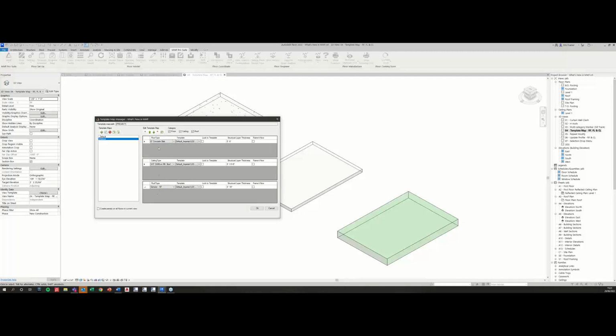I've got my Revit family types here. I've got my templates that I can define. I'm going to go ahead and choose my 6-inch LGS for my floor, my 3-inch LGS for my ceiling, and the 10-inch LGS for my roof. Okay, so now I've added the maps and I've chosen those for each category.